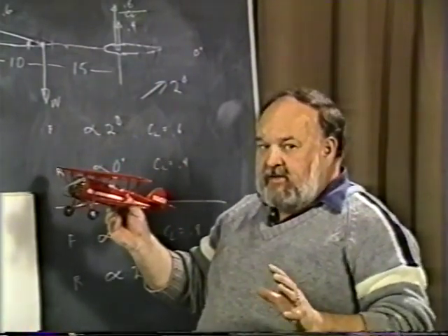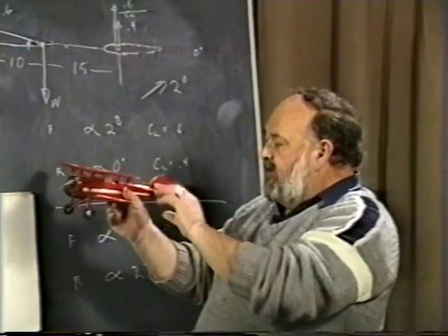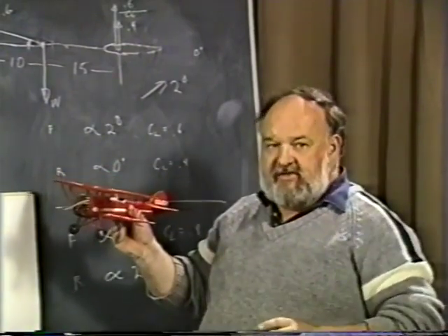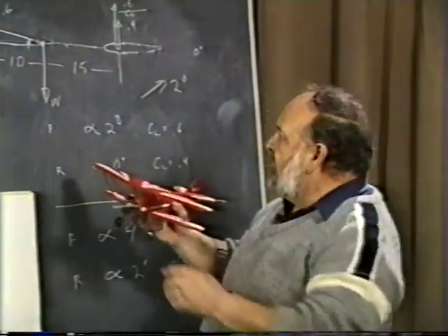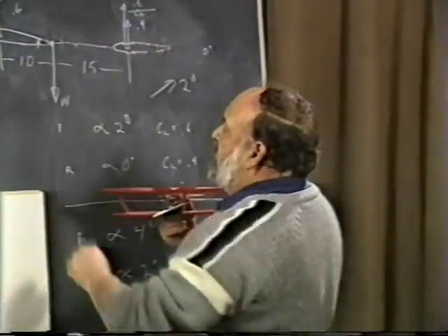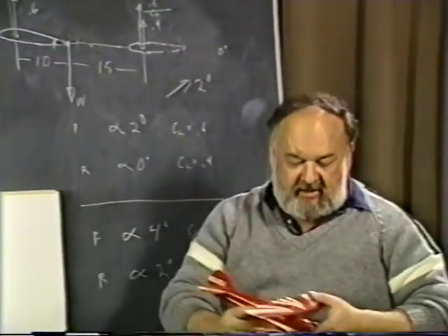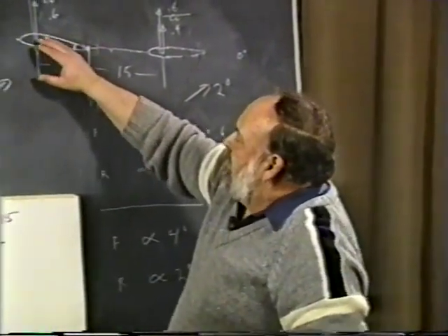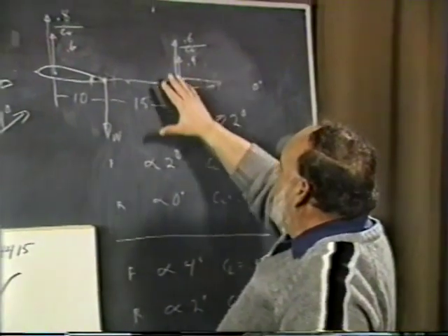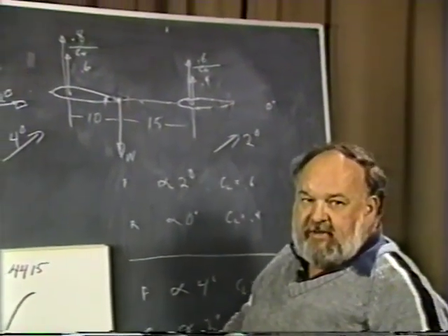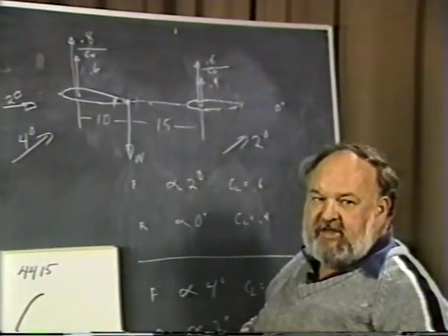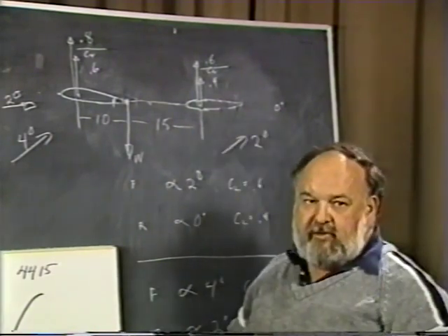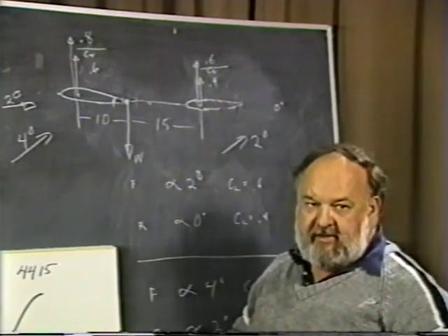Now, in fact, you could go so far as to say, let's have the wing flying along and the tail at an angle of attack that is producing no lift on it, none whatsoever. Well, now the balance point has to be right under the quarter chord of the wing. And in that case, it's very easy to see that if the weight is totally under there, the rear section is lifting nothing, but as soon as it gets any form of a change of angle of attack, whether up or down, it will immediately try and restore the wing up or down in the same particular way.